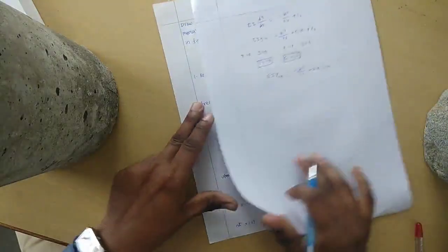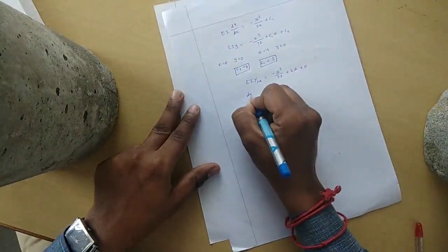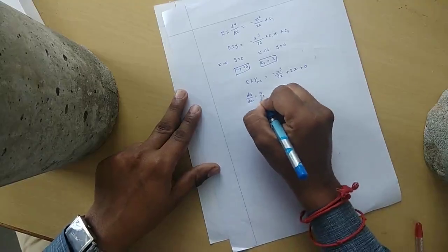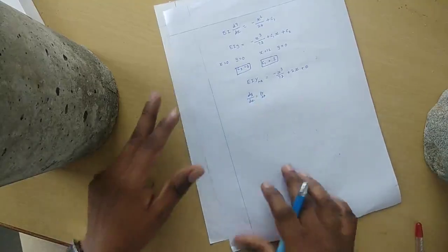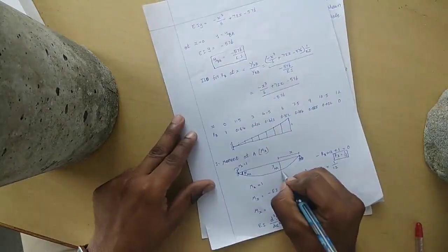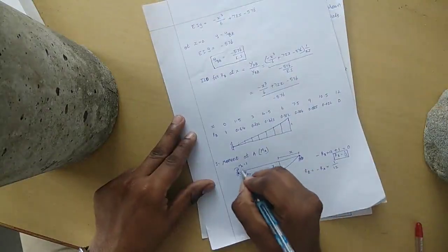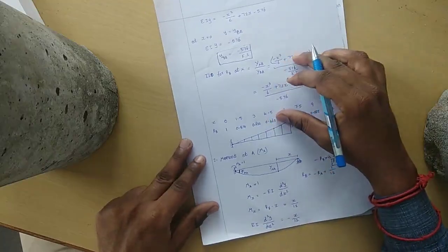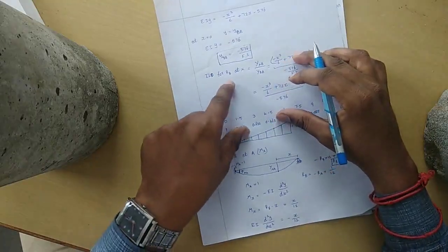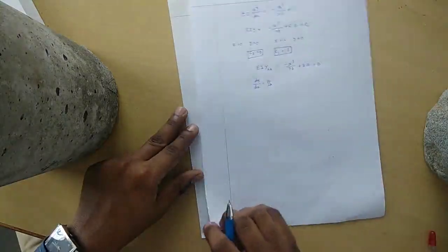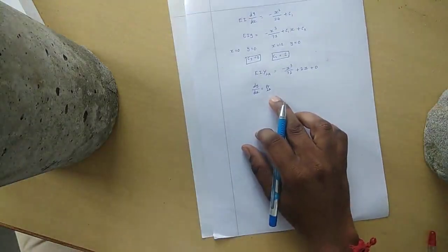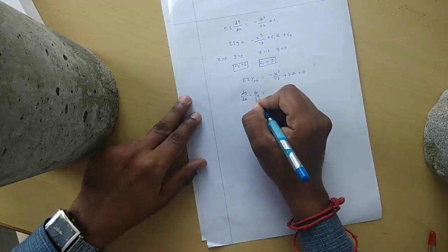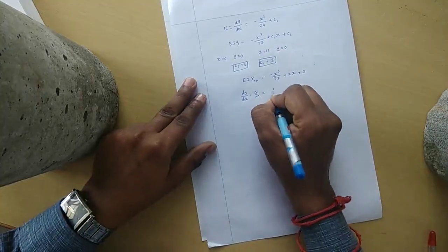In order to find that, what I need is dy by dx. It is nothing but theta xa, that is displacement or slope at point x due to the moment at A. Because in the previous step we needed to calculate the force, so we directly calculated the reaction force. Here we need to calculate the moment, so we are going for the rotation. So theta xa will be equal to, we know, 1 by EI.